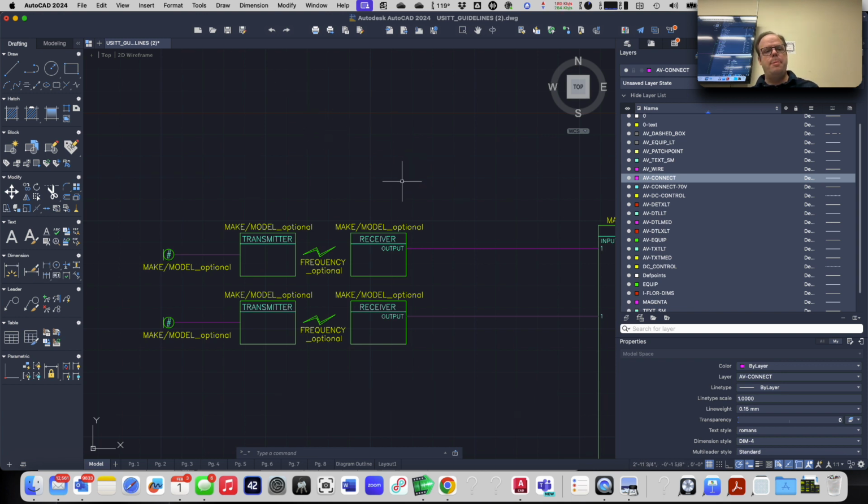What is your reasoning behind making the choices for the base point? Because I'm interested in the spacing here between the top one and the copy of it below. And so I want to click on the top of that box so that when I'm moving it, where I'm dragging it to is where the top of that box is going to end up in the copy, and then I can know that that spacing is what I want it to be. It would work if you snap to the bottom of it too, but then at least my mouse is next to the place where it's going to end up going, and that makes more sense to me.